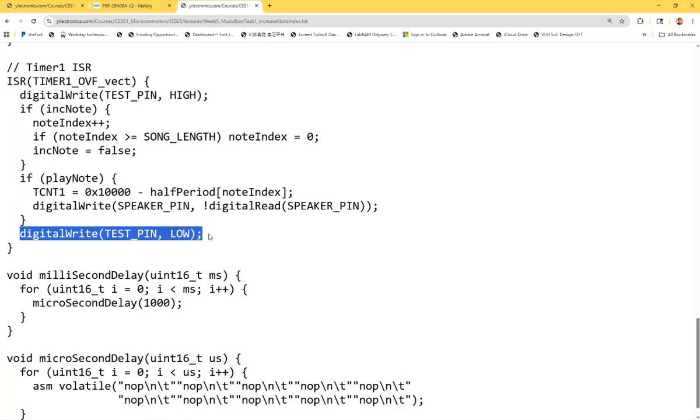It's creating a pulse. If you connected pin 13 to an oscilloscope, you will see a pulse, which means it enters the ISR. So you know that part works at least. So the problem is somewhere else, and you can start debugging something else instead of the ISR. Okay?